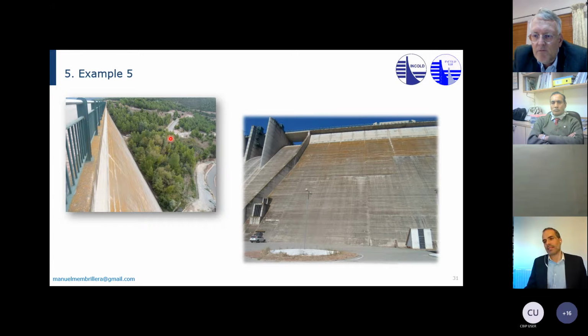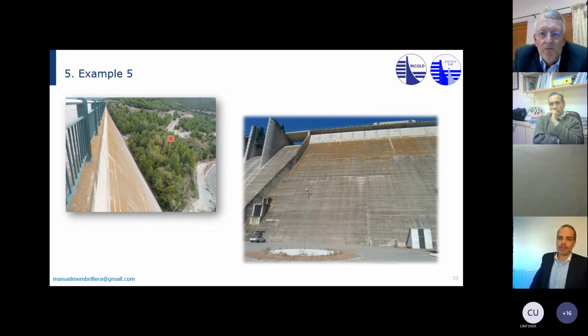And the problem is sandstone is really, really hard to grout. It's very difficult to grout sandstone rocks. And so with all the grouting works, tons of cement and grout were going into this fault, these joints in the rock, and it was useless.